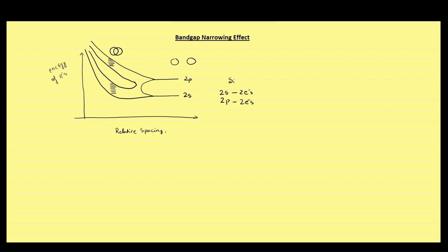But this concept is not restricted only to semiconductors. As we discussed in the last lecture, in non-degenerate semiconductors the dopants are usually placed far apart from each other so that they do not interact with each other. For a normal non-degenerate semiconductor, dopants are usually mixed in the ratio of 1 to 10 to the power 8 atoms. It means that for 10 to the power 8 atoms of silicon, there is only one dopant atom.